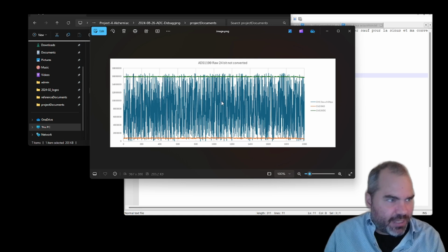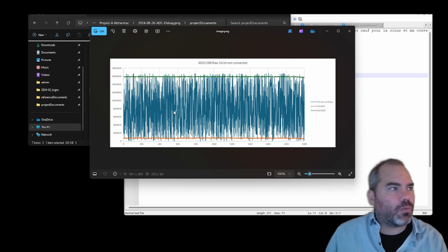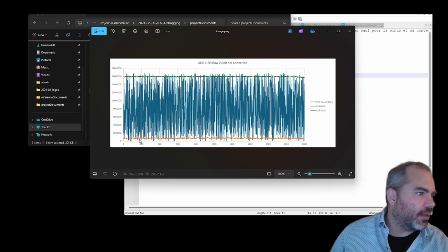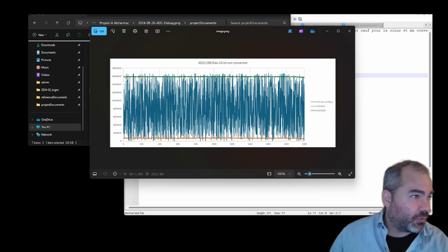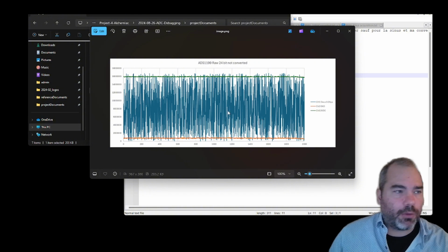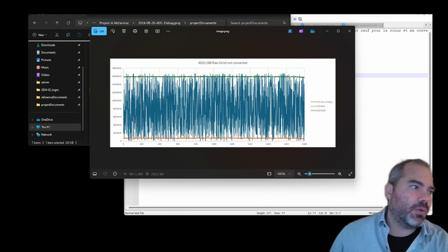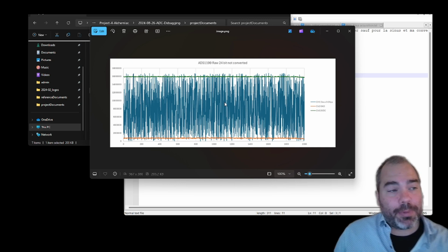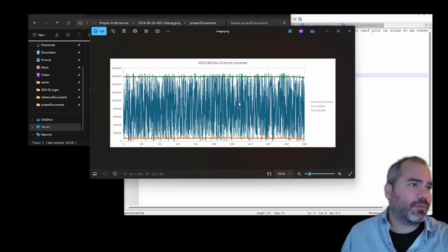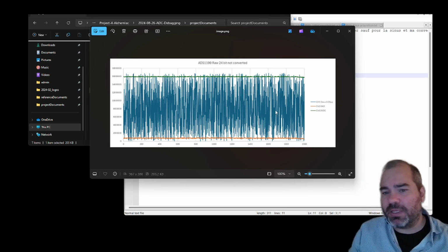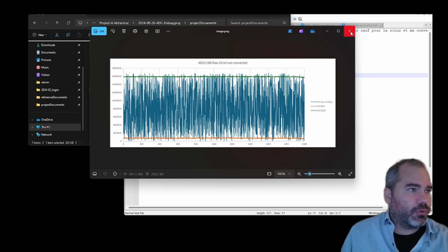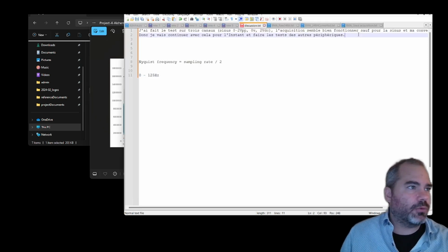So it seems like something's working, but there's an offset here. This one should be on 2 volts, technically. And we see that the 0.2 volt peak to peak is in between. So now, what's happening? That's what we'll need to figure out. But we have these pieces of information to say, hey, this is a problem we need to be fixing today.